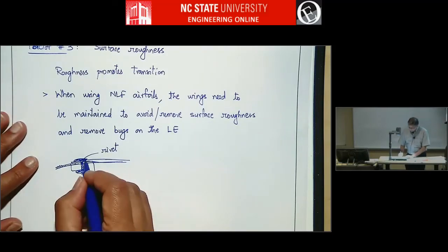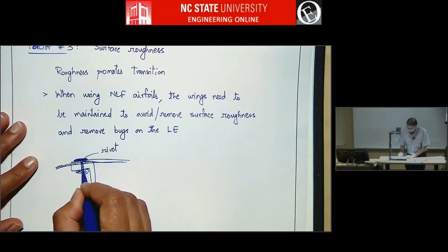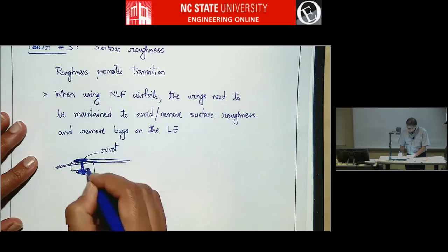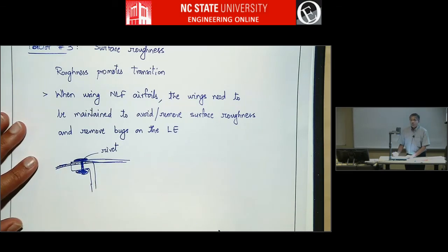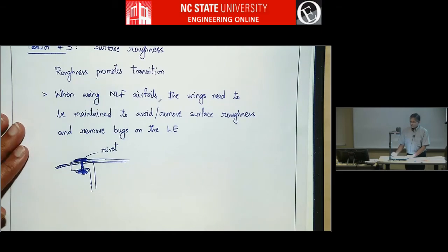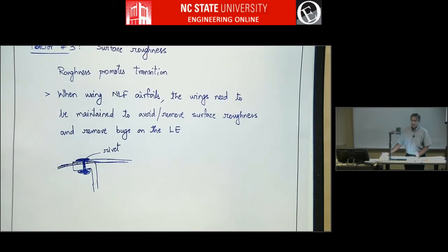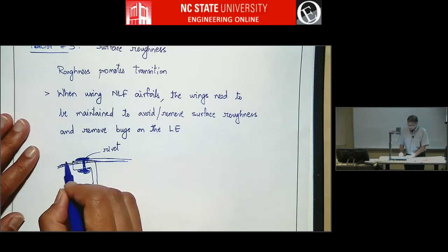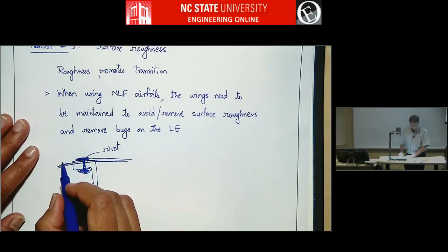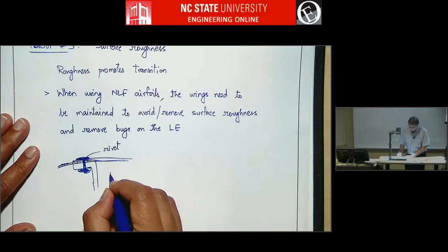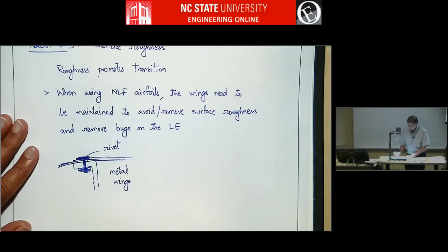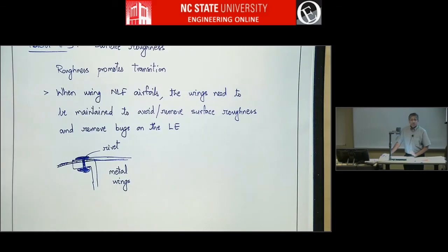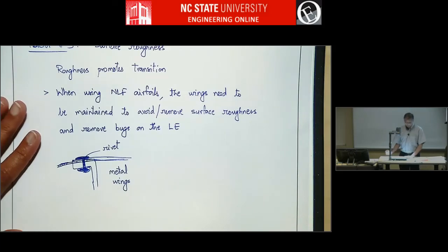Many of these airfoils were not laminar flow airfoils, and that's because these rivets and skin joints are imperfections, and at Reynolds numbers typical of those for manned airplanes, this would cause transition. So it's not possible to sustain laminar flow with such imperfections.